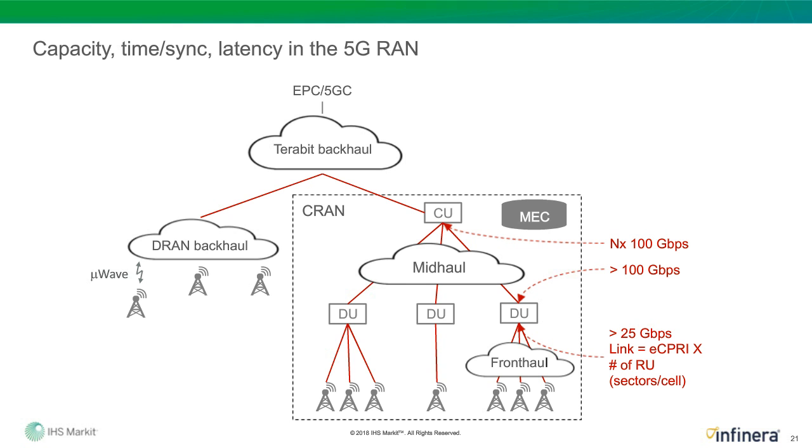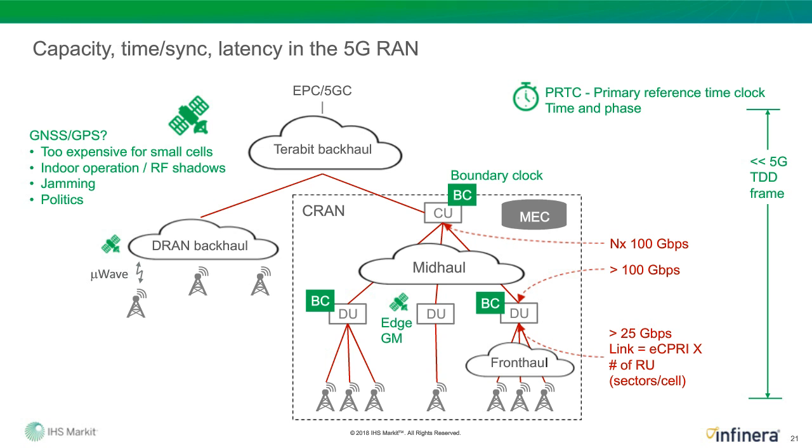However, in 5G, timing is everything. With 3G, it was enough to assure the handoff. In LTE advanced, timing was definitely more of a factor for radio coordination and interference management. Now, one way we could implement a very precise time network is to provide a GNSS, or global navigation satellite system, a GPS, at every node, so that you can have the precise time of day without any differences. But this isn't practical.